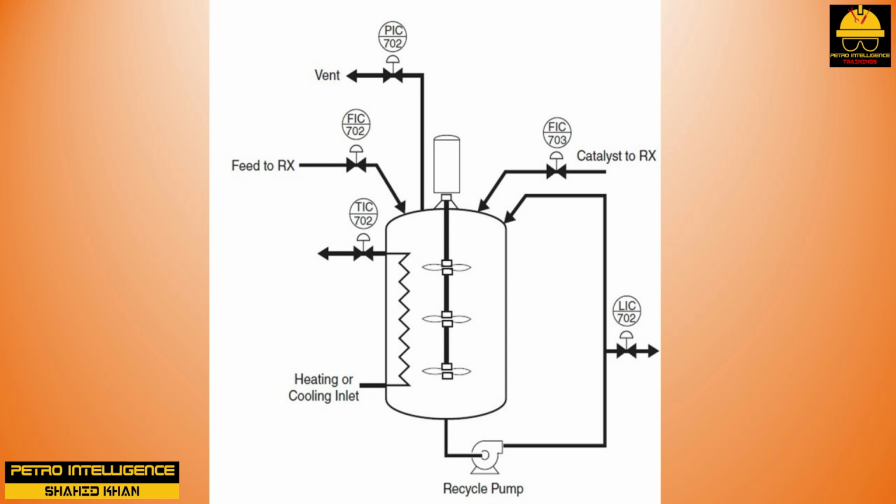Process variable alarms will be activated by analytical, composition, pressure, temperature, flow, level, and time variables. Rotational speed on the agitator may be fixed or variable. A series of interlocks, permissives, and alarms will engage during operation and will provide a support network for the technician. A series of process video trends will be displayed to track each of the critical variables. Samples are taken frequently to ensure product quality. Stirred reactors are connected to off-specification, or off-spec, systems that allow flexibility in switching between prime and off-spec situations.